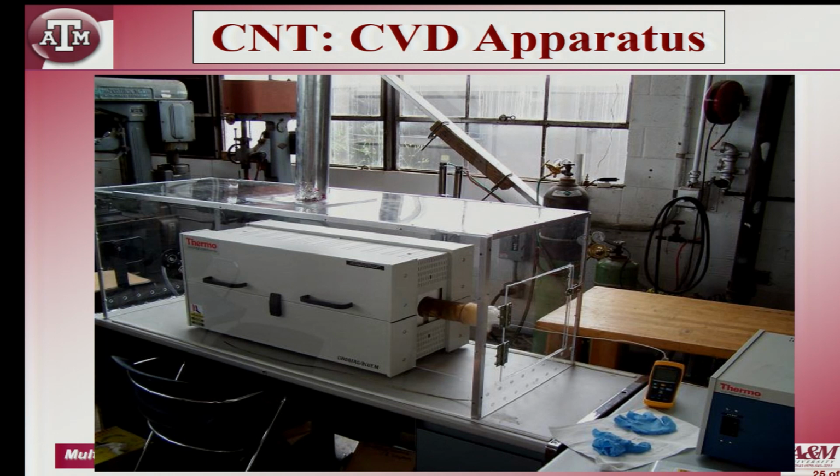purely nitrogen atmosphere, then we heat it up to 800 degrees Celsius while the nitrogen is flowing, and then once it hits about 800 degrees we mix a little bit of acetylene with the nitrogen and flow it into the system. And at that high temperature the acetylene, wherever it finds the iron, it reacts to form an iron carbide, and then it saturates the iron with carbide, and then the carbide precipitates out, and as it is precipitating out the catalyst of course remains pure, right. A catalyst never participates in the chemical reaction, and so as the carbide is precipitating out of the catalyst, it forms into a carbon nanotube, okay, and it grows at about a micron a minute.